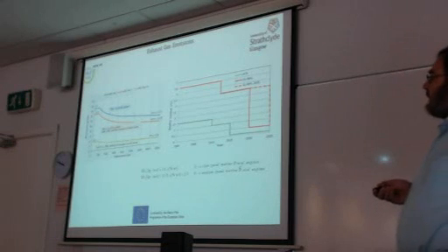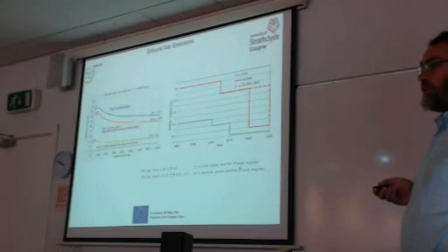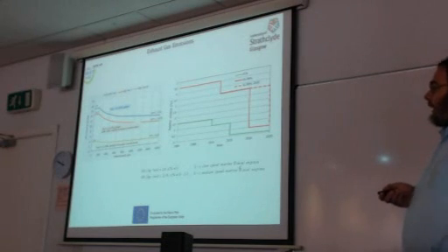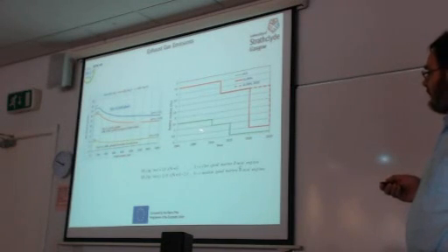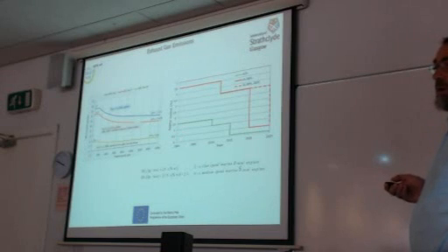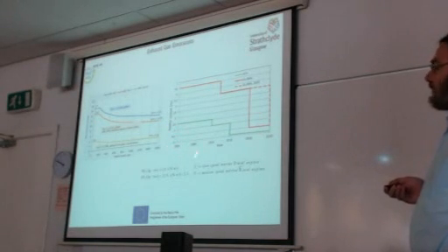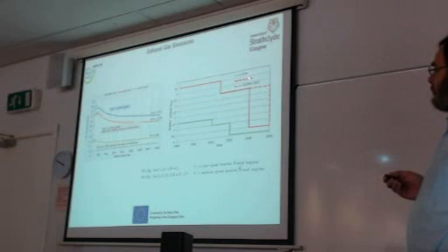2021 onwards, there is a large possibility that Tier 3 will come into effect, although it was to come into effect from January 2016, but this was postponed for some years. So we need to have in mind that this will result in a large pressure for the engine manufacturers, and then we need to know that there are limits also for the sulfur content of the fuel. Actually, the limit was introduced to decrease the SOx emissions.